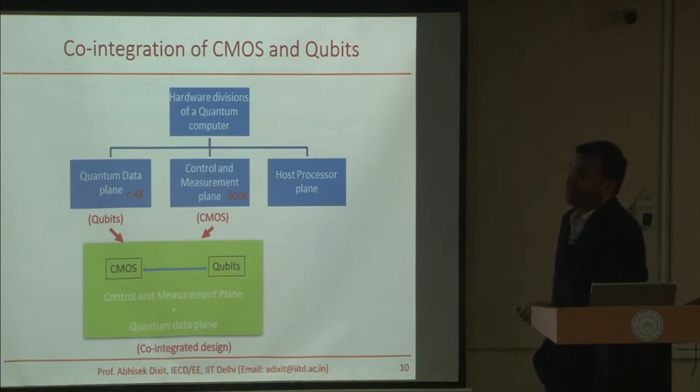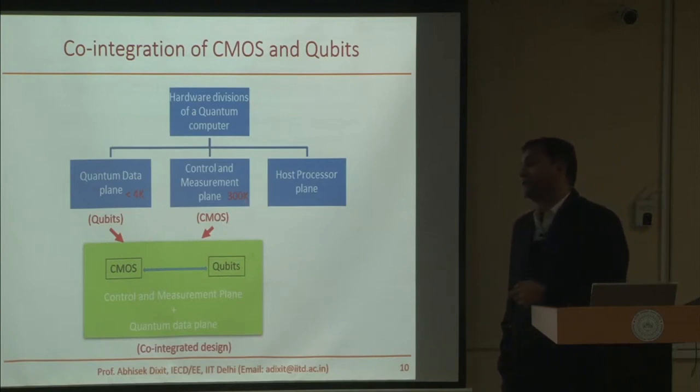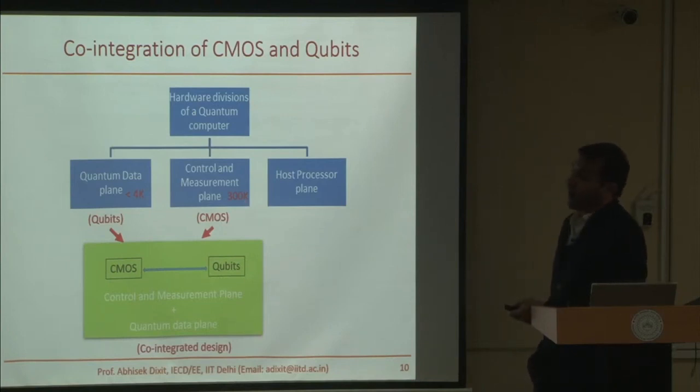You can detect quantum oscillations. So you can use an advanced short channel MOSFET or FinFET as a single electron transistor. If you are at sufficiently low temperature, how low will depend upon charging energy of your transistor, depending upon the gate capacitance and the access resistance of the device.